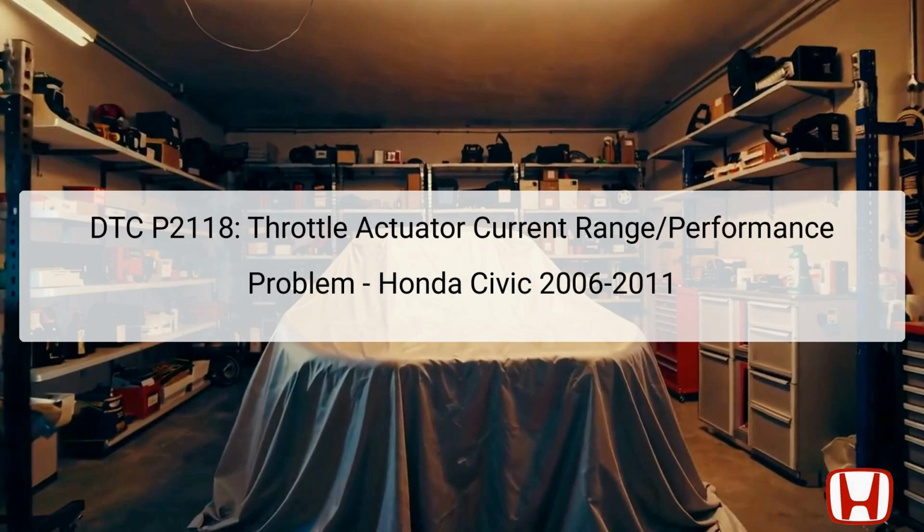The diagnostic trouble code DTC P2118 indicates a problem with the throttle actuator's current range or performance in Honda Civic models from 2006 to 2011. This error often signals concerns with the electronic throttle control system, which plays a vital role in managing engine performance based on driver acceleration input.